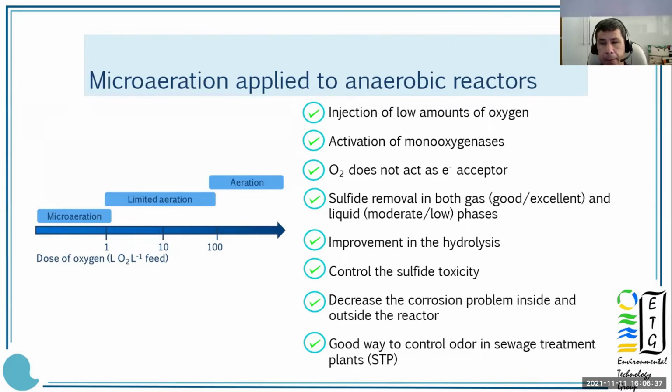But if we think about micropollutants removal or xenobiotics removal in bioreactors, this activation, which is caused by this very low amount of oxygen, is already enough to activate the monooxygenase, and this helps a lot to enhance the removal of these compounds in anaerobic treatments.